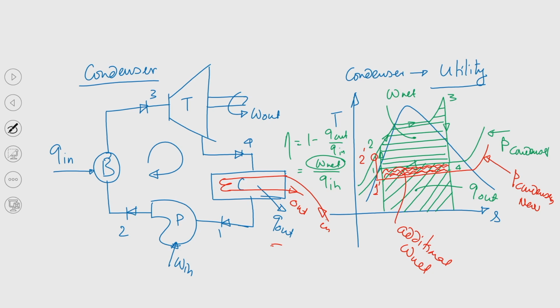Now, when the steam is coming out from the turbine, either the coolant will be allowed to mix with the incoming steam, so that the temperature of the steam can be reduced, and eventually the condensate that is collected will be pumped back to the boiler. If we have a direct contact type condenser, wherein this coolant is allowed to mix directly with the incoming steam from the turbine exit, then again we should have a kind of device in which an amount of condensate equal to the steam received from the turbine exit will be pumped back to the boiler, and the remaining amount will be transferred back to some other place.